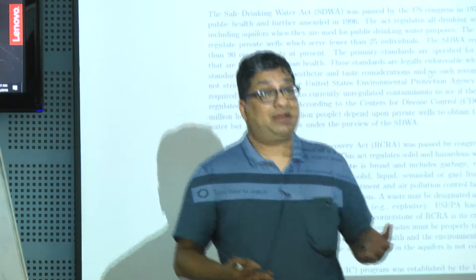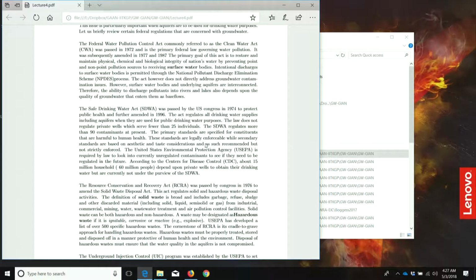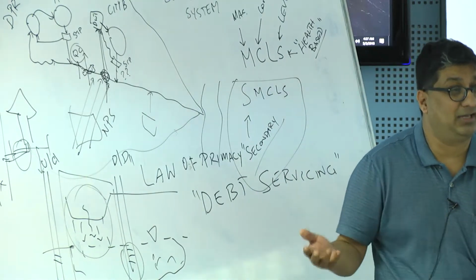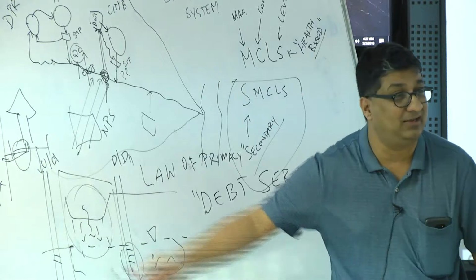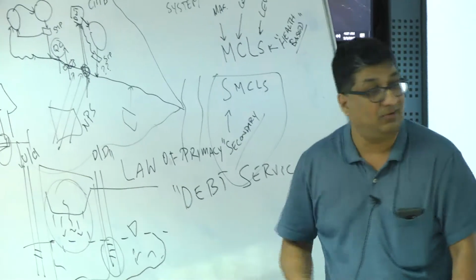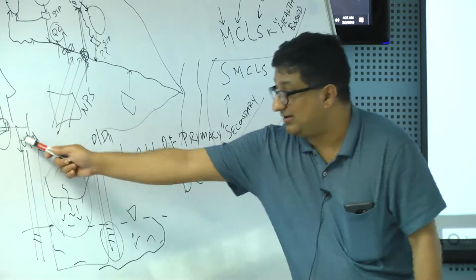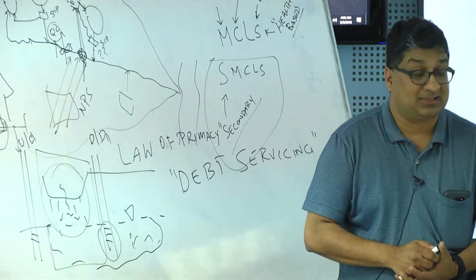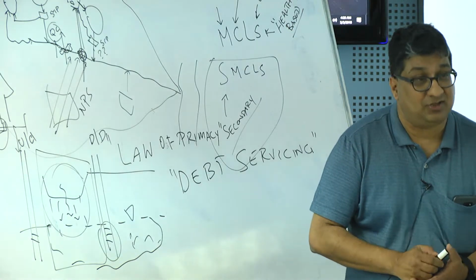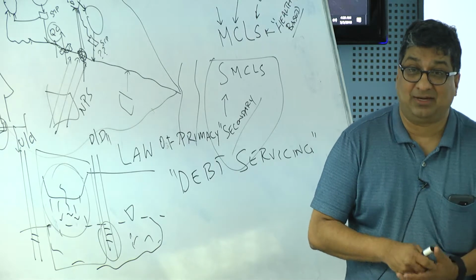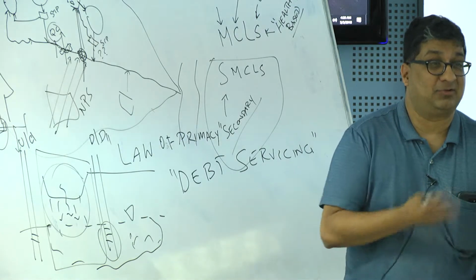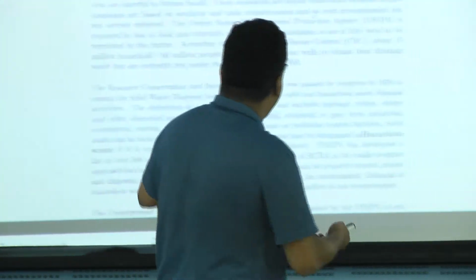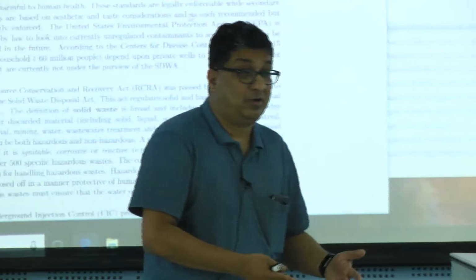Usually, what they clean it up to is they'll go look at what this up dip well looks like, or that's what the baseline is. It says naturally, if I didn't have this facility here, this chemistry would be very similar to this chemistry. So if I clean it up back to this chemistry, I'm good. Okay. And a lot of times even that is very challenging, because once you contaminate a site, restoring it back to that position can take several years.